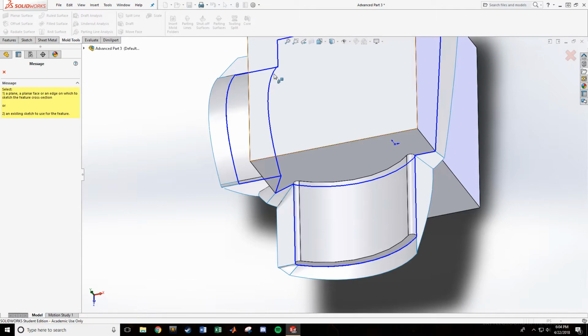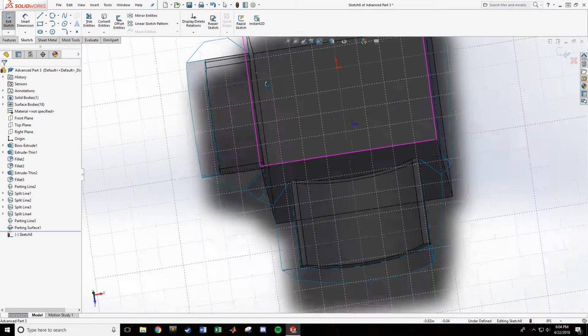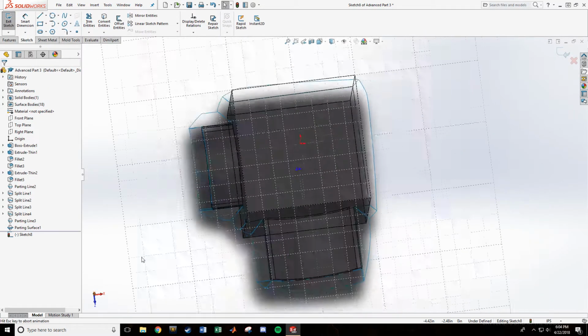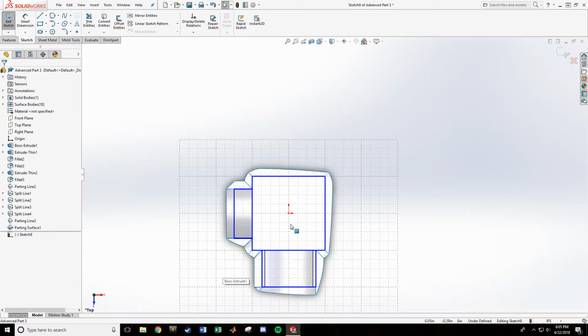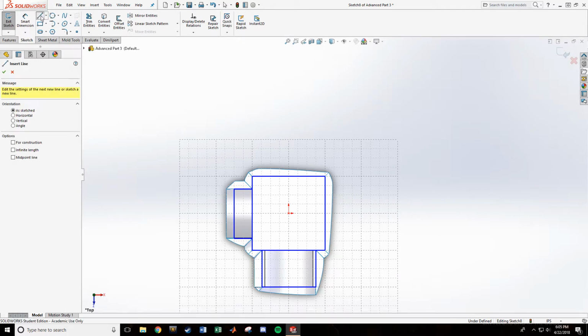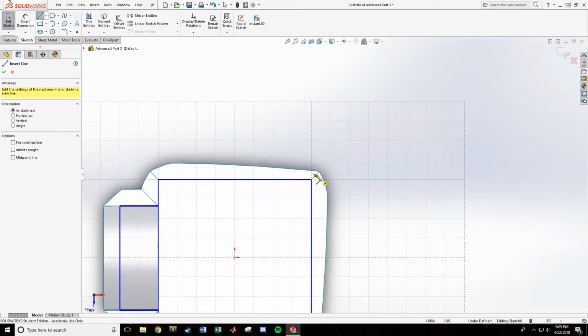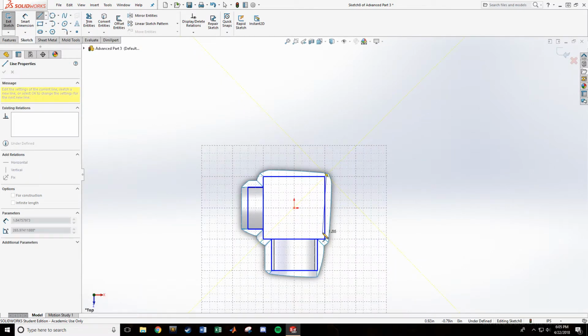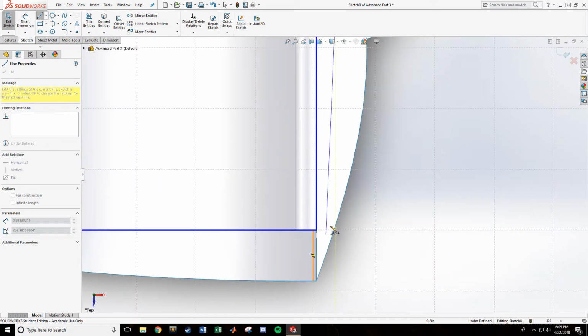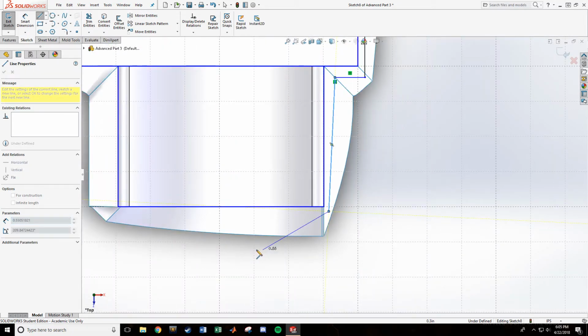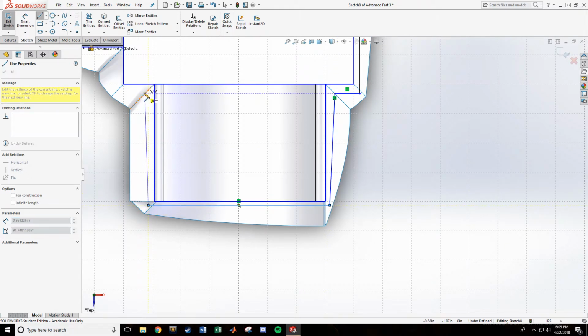We'll now do a tooling split. And when you deal with more advanced parts that have a very interesting parting surface like the one we have here, it's really important to make sure that your mold goes all the way around without exceeding the parting surface. So what I'm going to do here is, instead of just drawing a rectangle, I am actually going to draw just a really awkward shape all the way around.